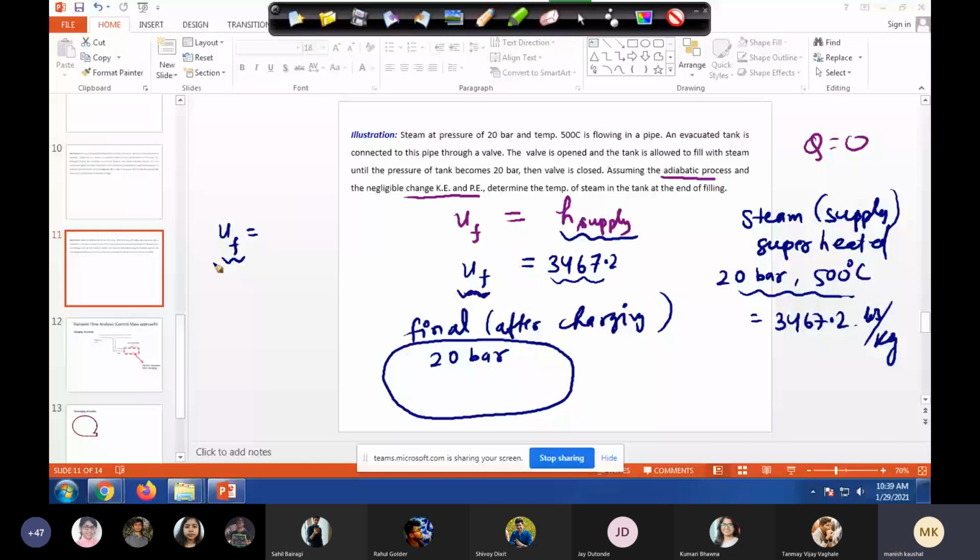Yes. Anyone? Any suggestion? So we have to see where the enthalpy is lying. Yeah, we have to guess the temperature. So basically, first of all, you have this H table and V table, right? Of course, for that given pressure and saturation temperature. Then you calculate a U table, and then you see whether your UF lies, and then you have to interpolate.